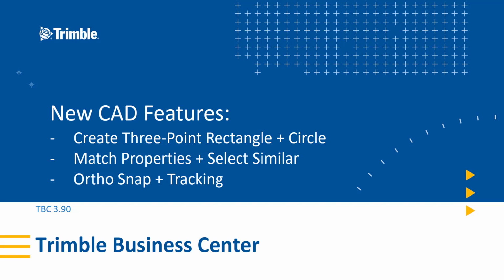Welcome to the TBC version 3.90 feature video. This video goes over some new CAD features that we've added in Trimble Business Center version 3.90. Those features include creating a 3-point rectangle and circle CAD element, matching properties and selecting similar from CAD geometry, and Ortho Snap and Ortho Tracking modes.